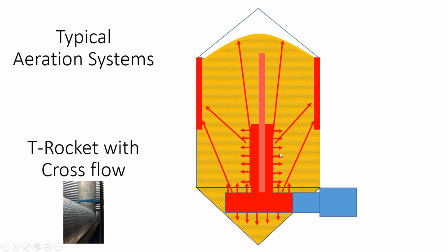out of the bin. The real goal with this design is that we want any air that is injected to have a path out of the bin that is very nearly half the radius. So you can see here, this is a sidewall vent, and basically the air can flow horizontal straight towards us into this sidewall vent and out, and here air can flow up to the other sidewall vent and out.